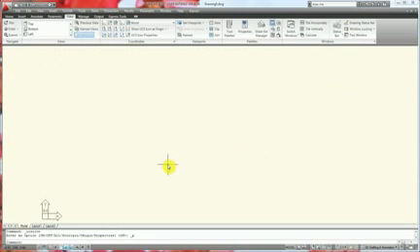Once we have done that, we're going to start working on our bracket. Now there's two ways to input lines in AutoCAD. There's both Cartesian form and polar form. Cartesian form has to be given coordinates of x and y in the case of this two-dimensional drawing, and polar form has an input of a radius and an angle. So we're going to use both of these when we make this bracket.